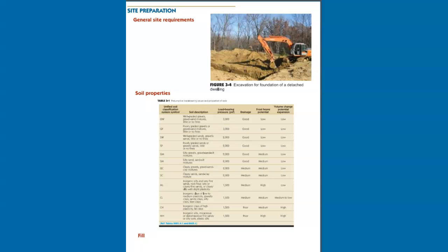Fill materials are typically sand, crushed rock, clean gravel or a mix of granular materials. Fill material may contain finer particles that fill voids and help bind the larger elements together. Materials with rounded edges such as river rock or pea gravel are not usually considered suitable for structural fill. The engineer's design specifies the maximum thickness of each layer of fill, called a lift, prior to mechanical compaction. A technician tests the compacted fill to verify that it meets the minimum compaction and design specifications.